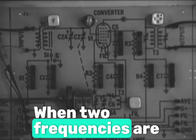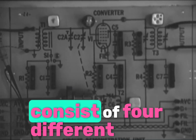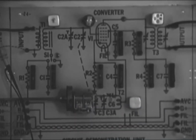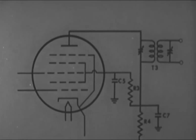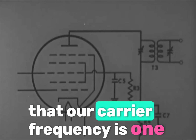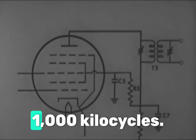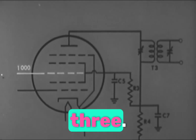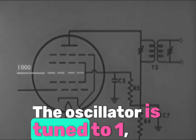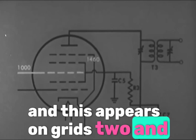When two frequencies are fed into any non-linear device, the output signal will consist of 4 different frequencies. An example may help to make this clear. We have already said that our carrier frequency is 1 megacycle, or to put it another way, 1,000 kilocycles. This is applied to grid number 3. The oscillator is tuned to 1460 kilocycles, and this appears on grids 2 and 4.